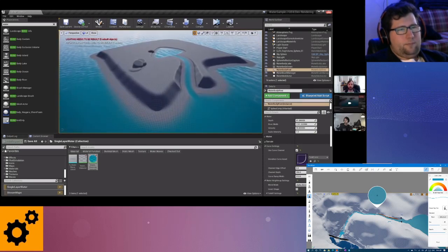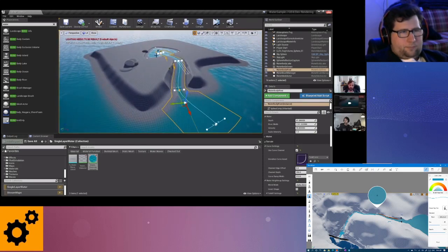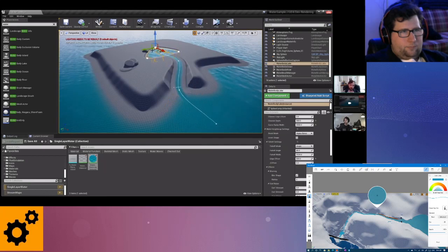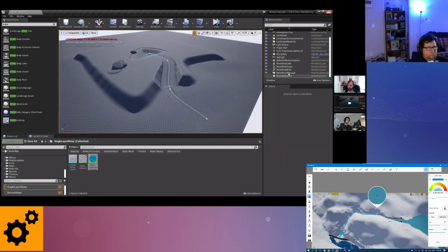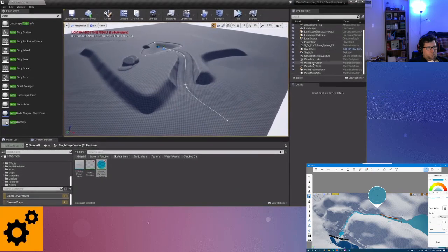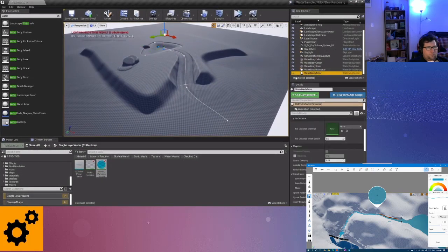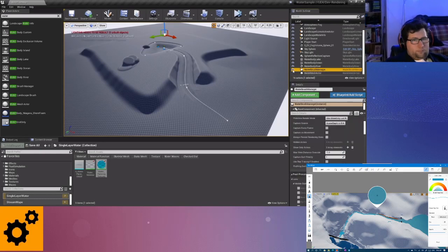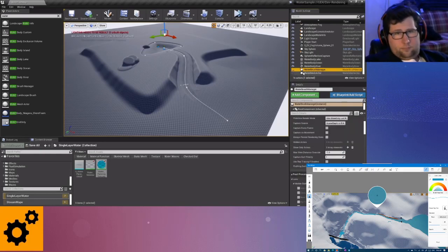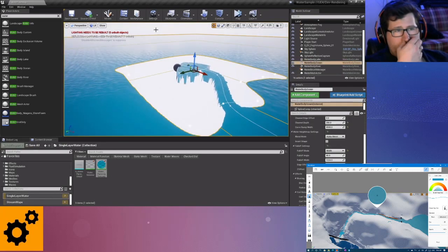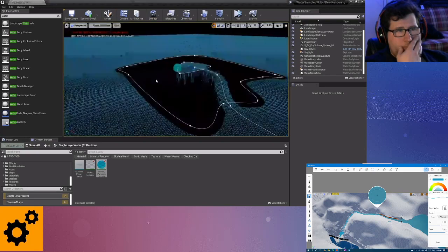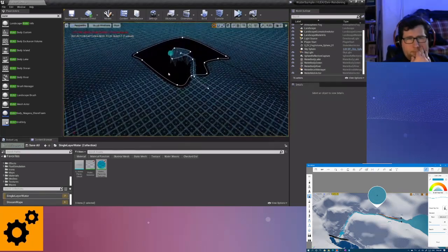And I guess I'll back up a step here and mention how these guys are all rendered. So these are all separate actors, as we mentioned. They're all just different water bodies, but they're all being rendered by the same actor. So in the world now, you'll see we've got a pretty simple scene. We've got our landscape and basic lights and our water bodies, but then we have this water mesh actor and also the water brush manager. We can ignore that guy. You don't really need to think about him. The water mesh actor, though, this is actually what's doing the final rendering for the water. So we can go ahead and jump into wireframe mode, and we can see that.